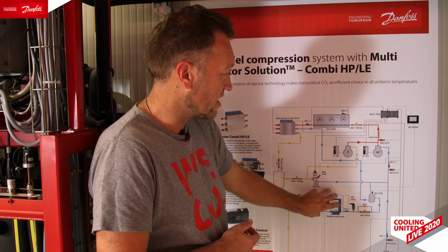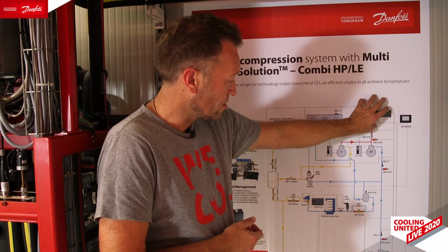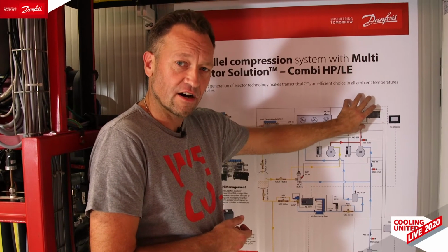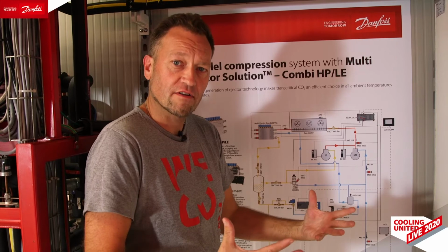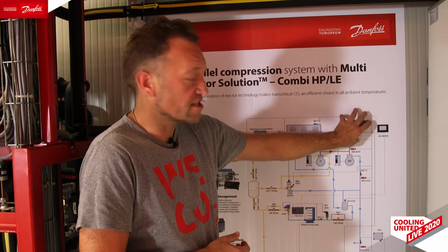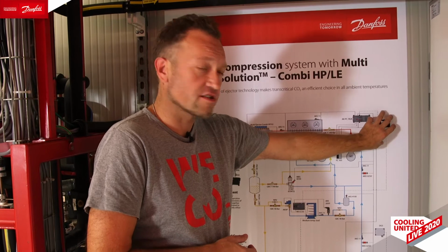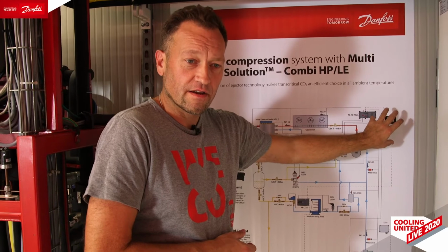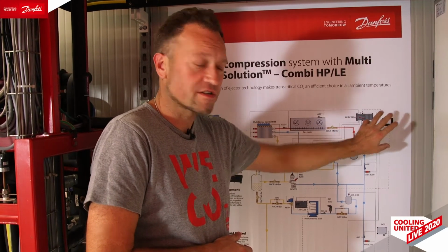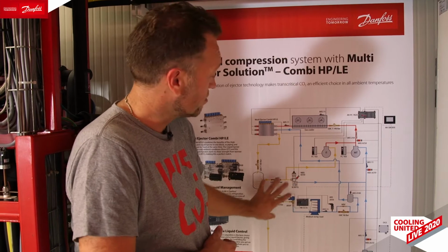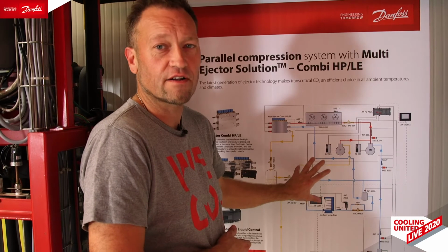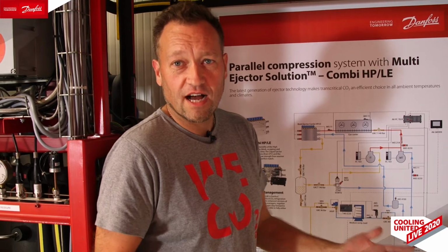This mode is changed by the pack controller, so we have a liquid switch on the accumulator, or the pack controller is detecting that now the liquid ejector is coming out of the operational envelope, and then as a precaution it tells the system manager, now we need to get the case controller, the evaporator controller, out of the adaptive liquid control mode with the droplets and go back to the dry expansion. So this is the way that we have optimized the full system, and also guaranteeing the safeguard of the system and protection of the compressors. So that's all about the CALM system.